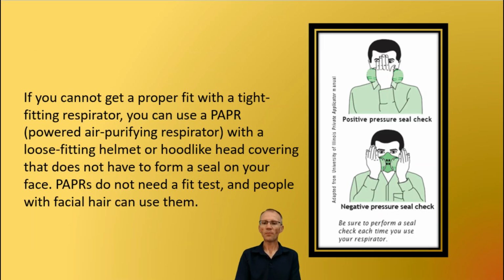If you cannot get a proper fit with a tight-fitting respirator, you can use a PAPR, powered air purifying respirator, with a loose-fitting helmet or a hood-like head covering that does not have to form a seal on your face. PAPRs do not need a fit test, and people with facial hair can use them.